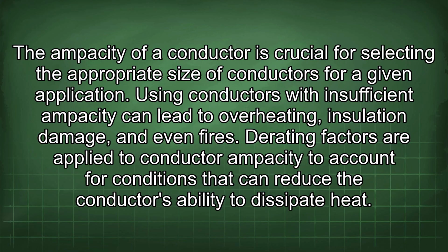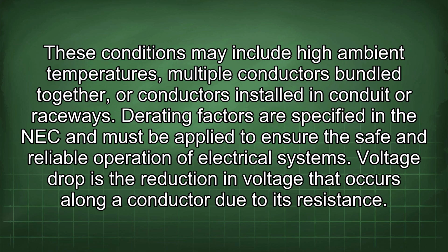Derating factors are applied to conductor ampacity to account for conditions that can reduce the conductor's ability to dissipate heat. These conditions may include high ambient temperatures, multiple conductors bundled together, or conductors installed in conduit or raceways. Derating factors are specified in the NEC and must be applied to ensure the safe and reliable operation of electrical systems.